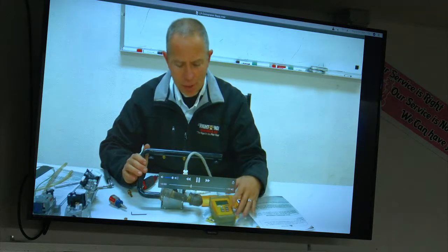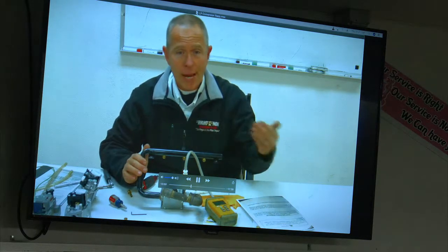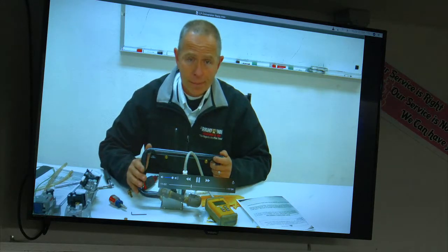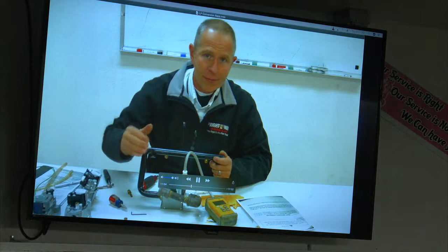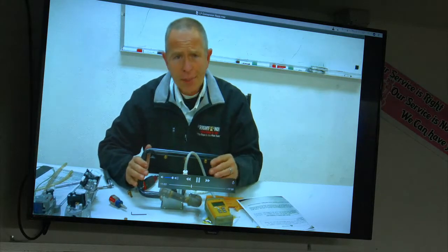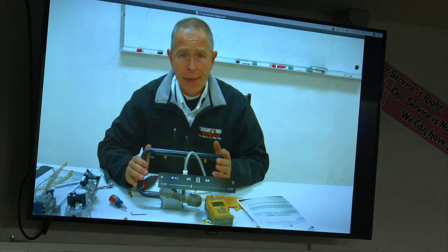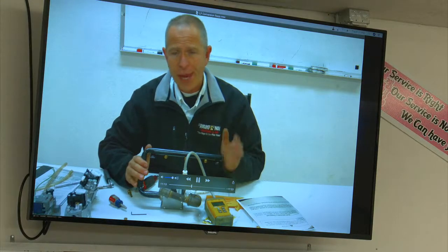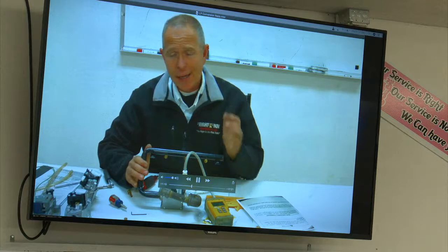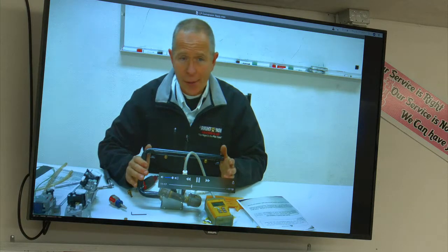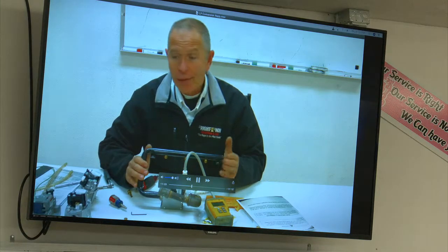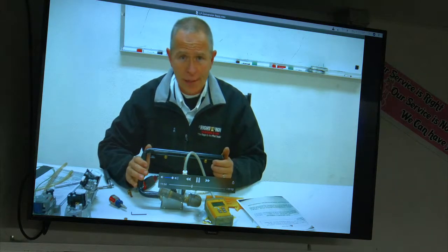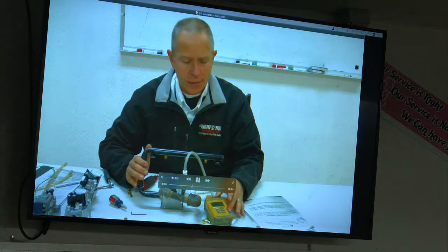So now that I am hooked up to the incoming from my tank or my meter side, I'm going to fire my furnace, making sure that the gas valve is turned on. And I'm going to confirm that with the newer ones, you have low fire and high fire, which it tells you. On the 80% ones, it will be a 5-minute wait or an auto or something of that nature. Some start off in high fire and others start in low and then shift over 20 seconds later. They all have different sequences.